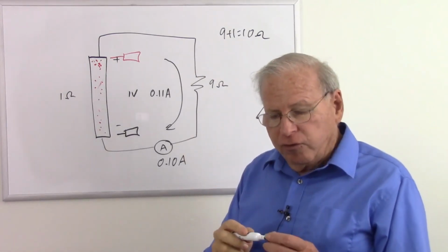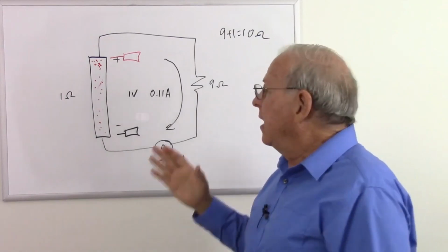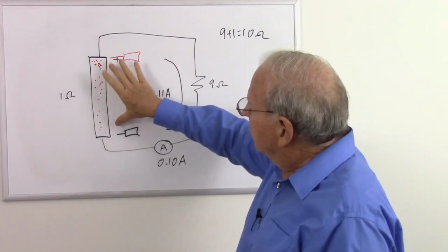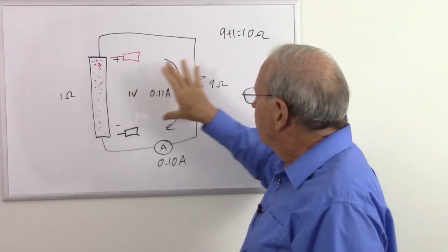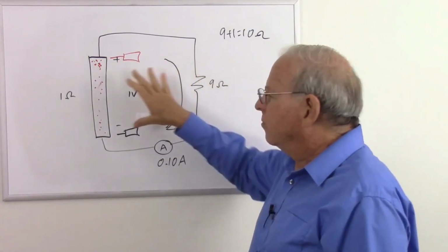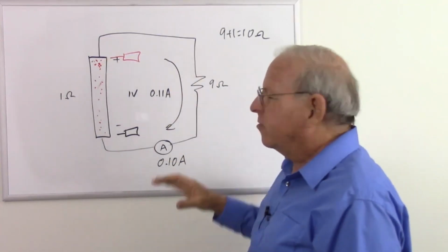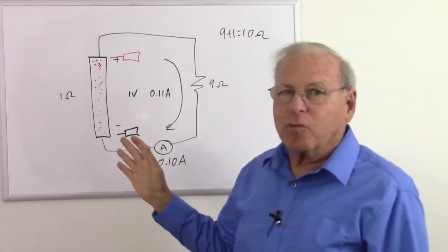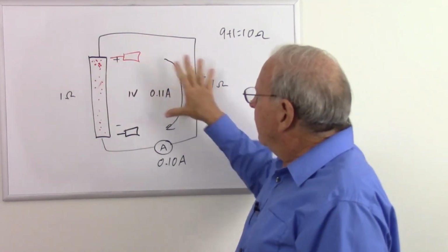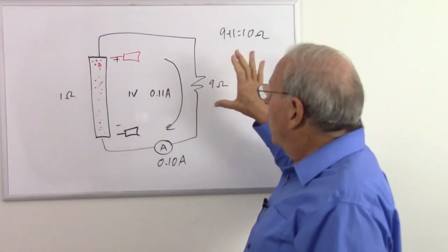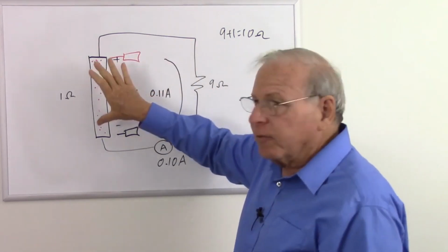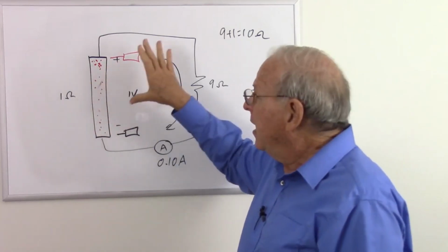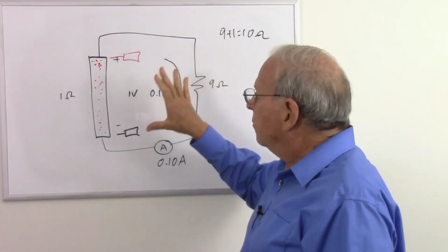And this is the crucial discovery that Georg Ohm made that made it possible for him to develop Ohm's law, because others who had come before him were getting the same problem here. We're not getting the voltages and currents to work with our resistance. They, of course, were using different measurements and different lengths of wire, but still, they weren't getting numbers that were linear. Ohm discovered that you need to take the resistance in your source, in his case just a thermocouple, here it's just a piece of wire, and put that in series with your load.